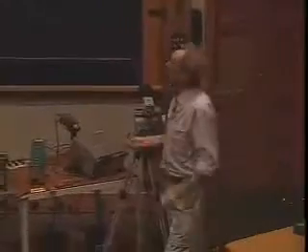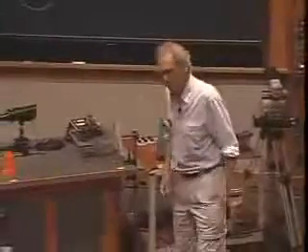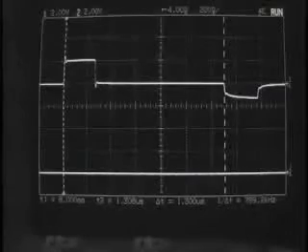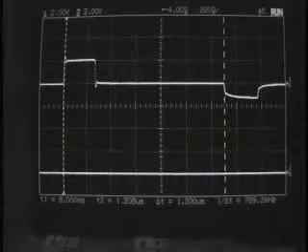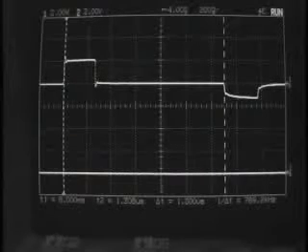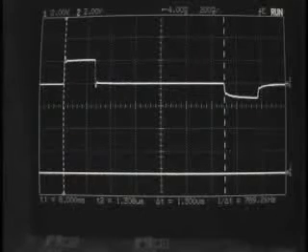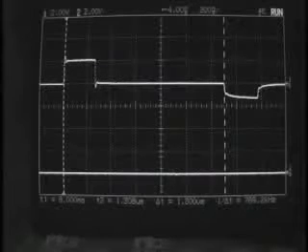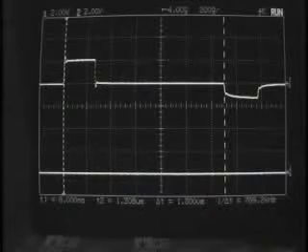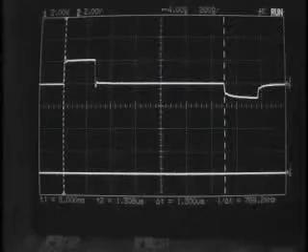All right, thank you, Marcos. Very thoughtful. So here is the pulse that goes in. And 1.3 microseconds later, between this line and this line, there is a marker here which says 1.3 microseconds. The mountain has returned as a valley. So this is the pulse where it enters, and then when it has come back.